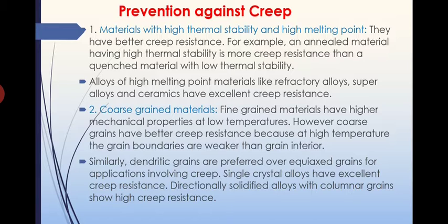So higher the melting temperature, more will be the resistance to creep. So all the material which is having high melting point will have resistance to creep. So if you want to prevent the creep, we have to use the material with higher melting point. Another thing is material with high thermal stability.